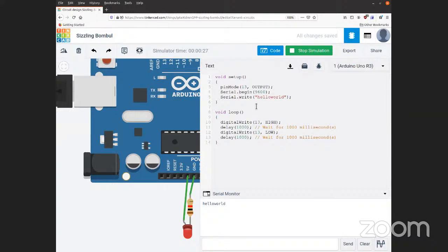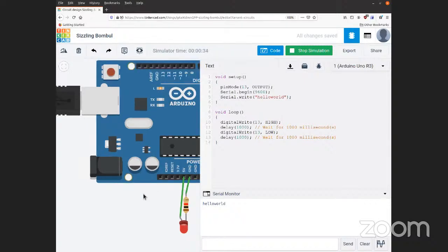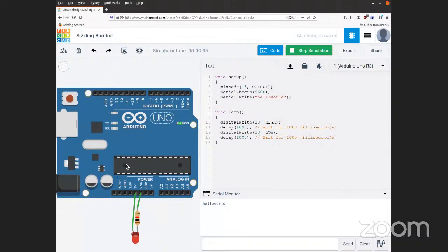Now, this printing, the idea itself is something to really take note of, because when you write a program, it's hard to tell what it's actually doing on the Arduino. So what you can do is have a print statement at critical points of your programs, or you can print out the values of variables to see where or which one is wrong. And this is called debugging, and you'll be using this skill a lot when you're first starting out.